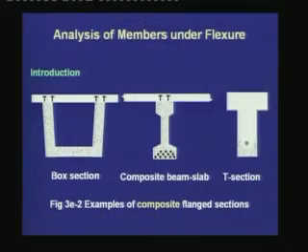There has to be proper shear connectors between the web and the flange to treat the section as a composite section. There can be various innovative types of composite sections. Some of them we shall see in the module under composite sections.